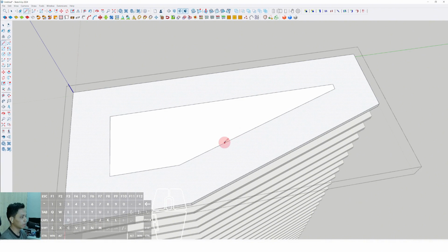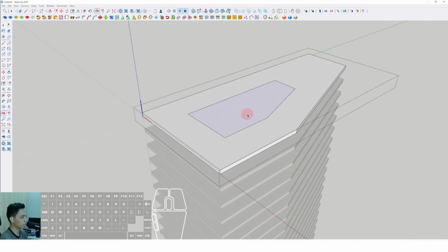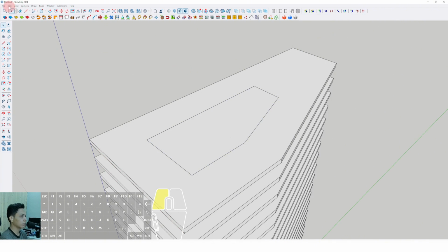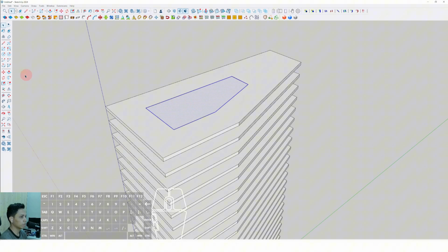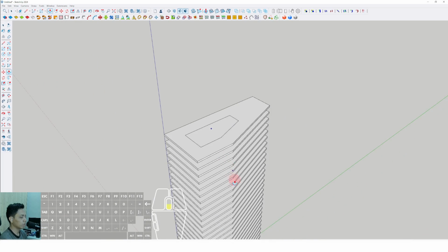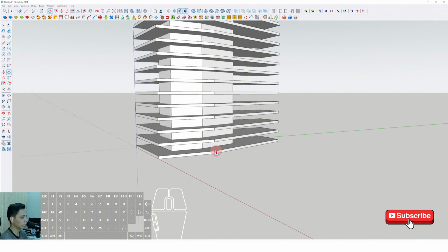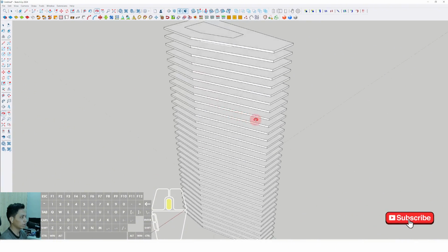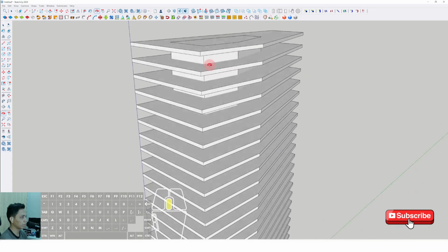and we can determine the limit of the core building on this position approximately, and just erase some additional lines and click this plane, edit, copy and exit from the group, click edit again, paste in place, and just push it to another level of the floor in this level. Okay, then we can see the core building and every single typical slab on this high-rise building.